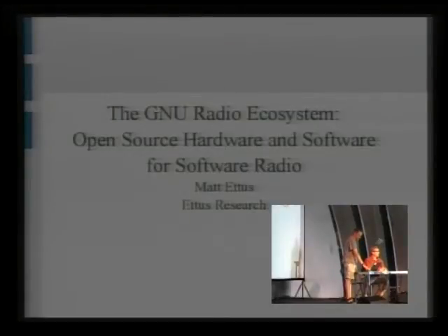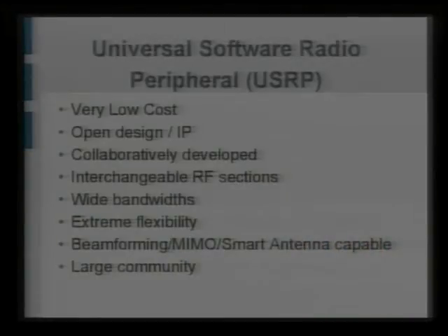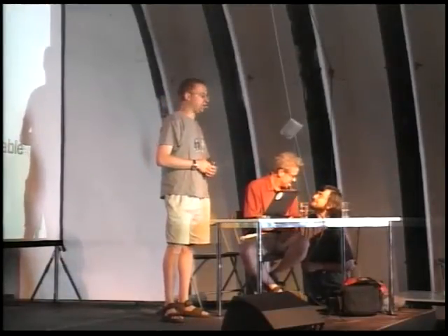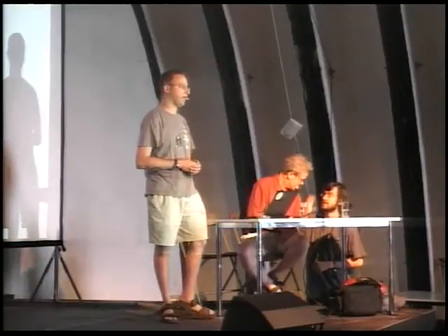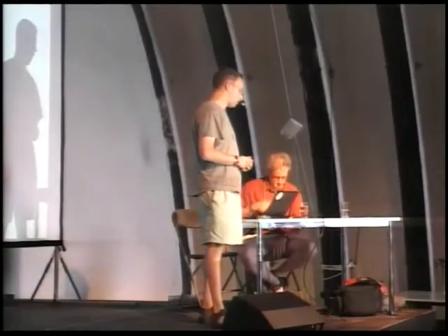Okay. So the hard thing with software radio is that you have to get your samples in and out of the computer, and no matter how much you process them in the computer, there's no real place to plug an antenna into it. And so about 5 years ago, I recognized this problem and decided that I wanted to create some open hardware to allow us to really do interesting things with software radio and GNU Radio in particular. And so I went about creating the USRP, or Universal Software Radio Peripheral.